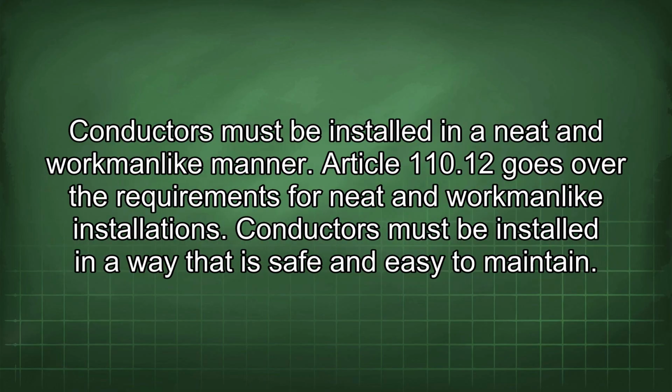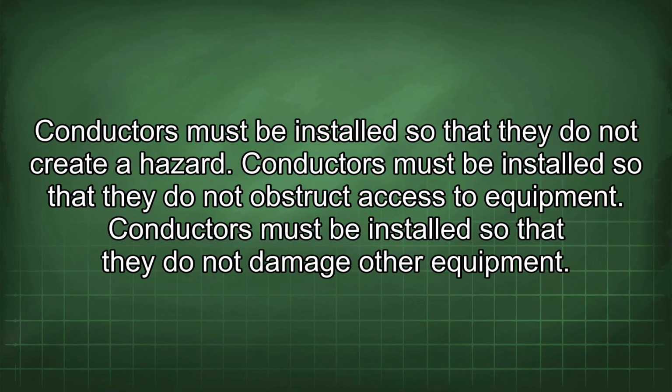Conductors must be installed in a neat and workmanlike manner. Article 110.12 goes over the requirements for neat and workmanlike installations. Conductors must be installed in a way that is safe and easy to maintain. Conductors must be installed so that they do not create a hazard. Conductors must be installed so that they do not obstruct access to equipment. Conductors must be installed so that they do not damage other equipment.